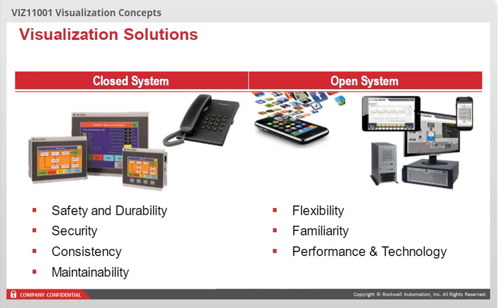Many of these systems are built on a standard Windows or similar commercially available operating system, allowing users to run an HMI project as well as many other compatible applications on the same PCs, tablets, or smartphones we use all the time. The newest, fastest, most advanced technologies are those developed on open platforms. Value-added solutions combine a controller and an HMI all on the same piece of hardware. On the technology curve, the latest operating systems, fastest components, and more memory make these solutions more suitable for either standalone or server-client architectures and improve data collection performance.